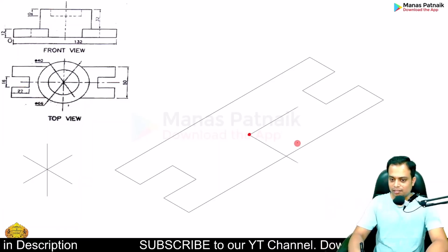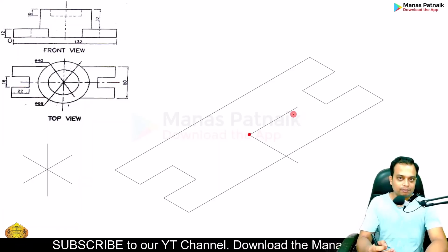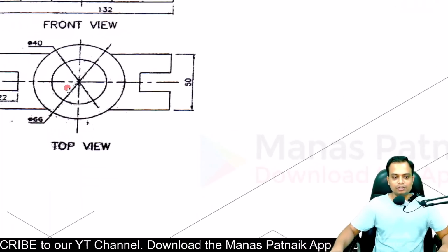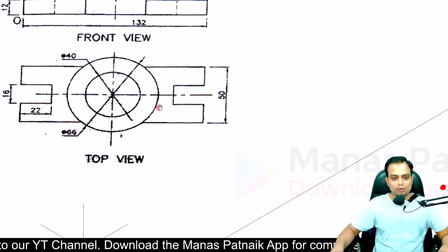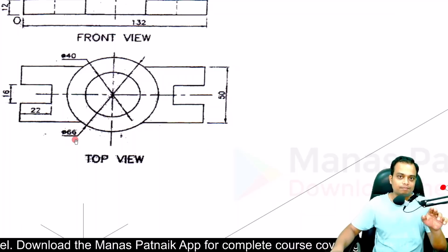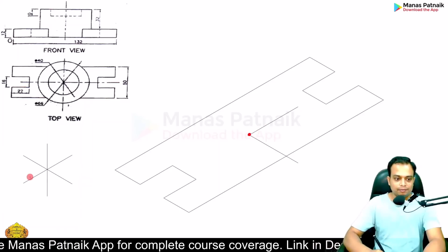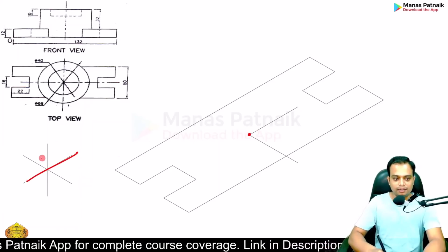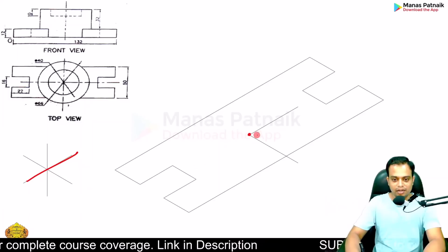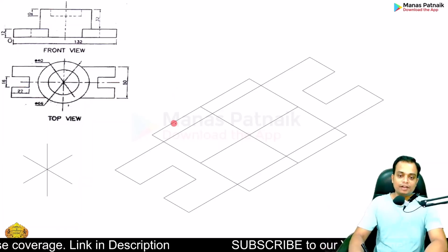Sir, what about these lines that you've just made? What are these lines? These lines actually represent the radius in isometric. Let me give you an idea of this. This larger circle over here has a diameter of 66. Half it, 33 is the radius. So 33 this way, and then 33 to the left, 33 above. Done, sir? Very well. Cover it this way.